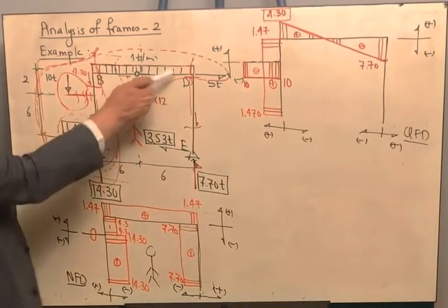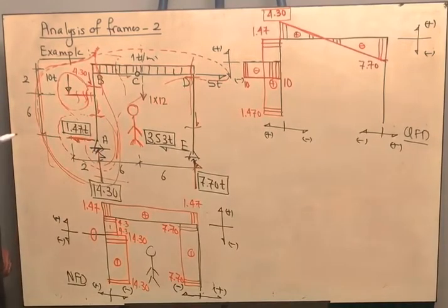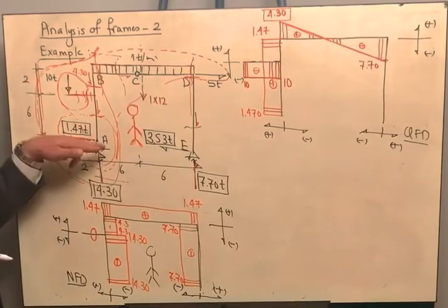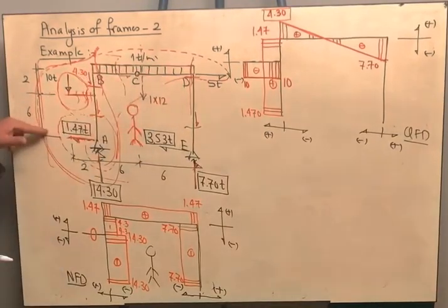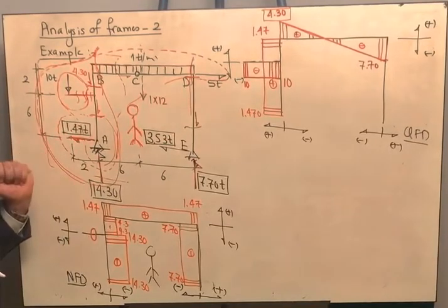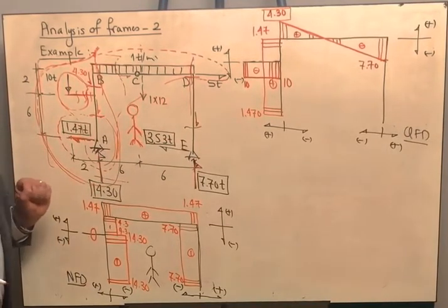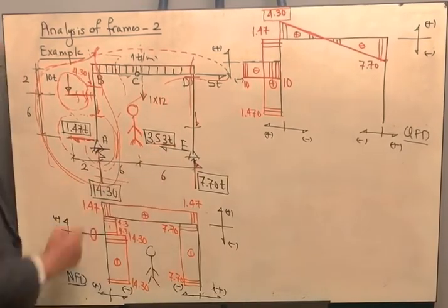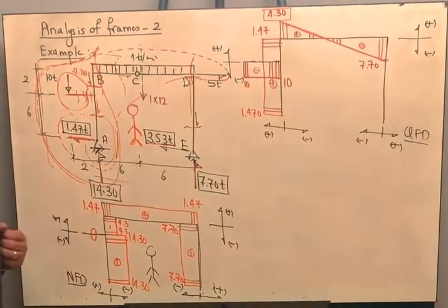How about the shear that it is causing there? It is negative because it is on my left hand side and downward. This force is on my left hand side and downward. So I'm having positive 5, negative 1.47, so it is positive 3.53. How did I calculate this very fast? Because I know that the reaction is 3.53. It should be equal to the reaction.